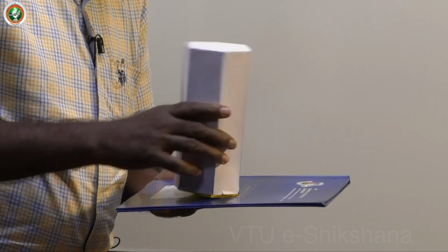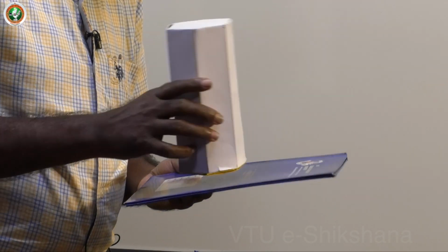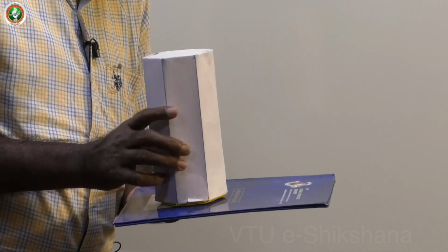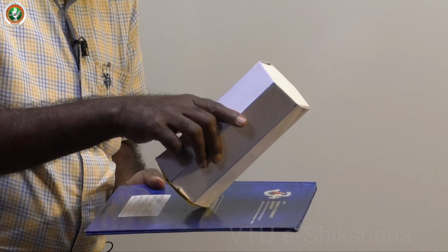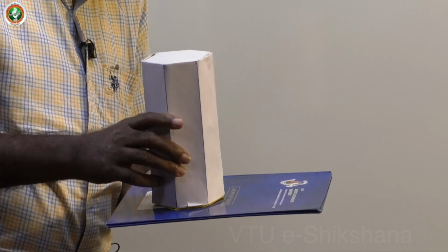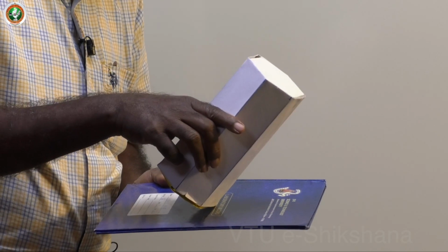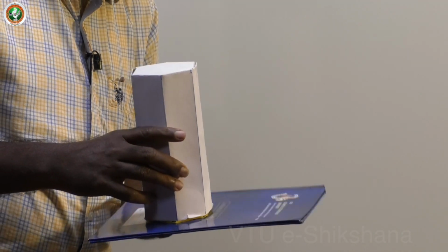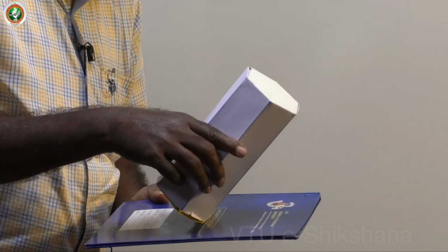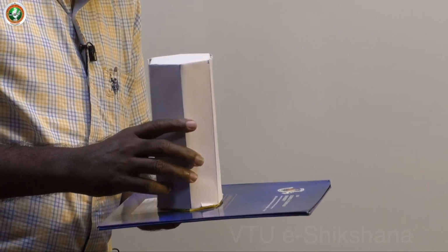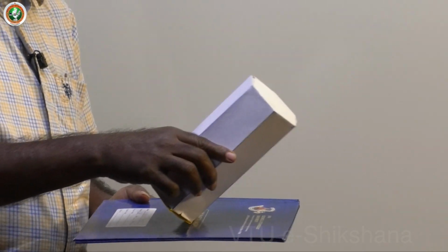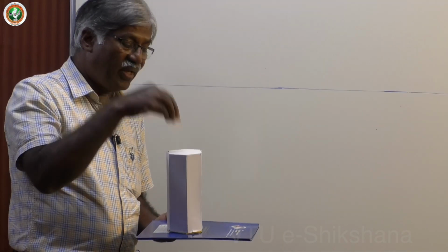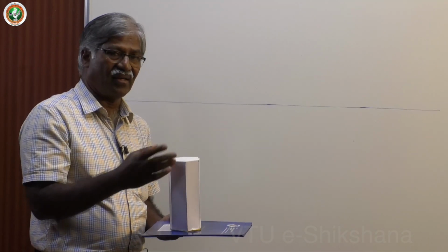So first position, second position. I have told you many times, why not like this? Orientation cannot be other than this, because if I do like this, it becomes corner condition, corner on HP, or any random situation also it is corner, because we are giving inclination only to HP. Unless the edge to be placed on HP is perpendicular to VP, we cannot normalize the situation. So first position, second position. Whenever you get inclination to HP, always make the axis perpendicular to VP. Now the top view is the true shape, that is hexagon, the cross section of the prism.